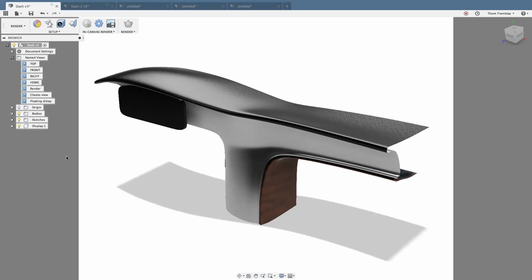Hey, Tom. Yes. Could you quickly explain a couple terms you were using, G0, G1, and G2? Yep. G0 is essentially where 2 faces meet at an edge, and that edge is sharp. G1 is tangent continuity, where a curve between 2 faces will just simply be worried about maintaining tangency as it goes from one edge to another.